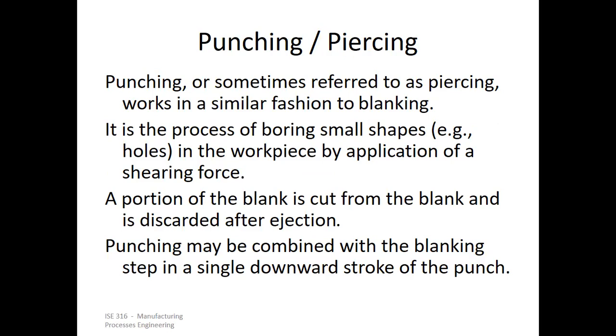As for punching or piercing, as we have said, it works in a similar fashion to blanking. How? Because it is basically a shearing operation as well. The dominant mode of deformation is shearing. It is the process of boring small shapes, for example holes, in the workpiece by application of a shearing force. In blanking, you had that blank which was removed as a useful product, right? But in some components, it may be required that a hole has to be created.